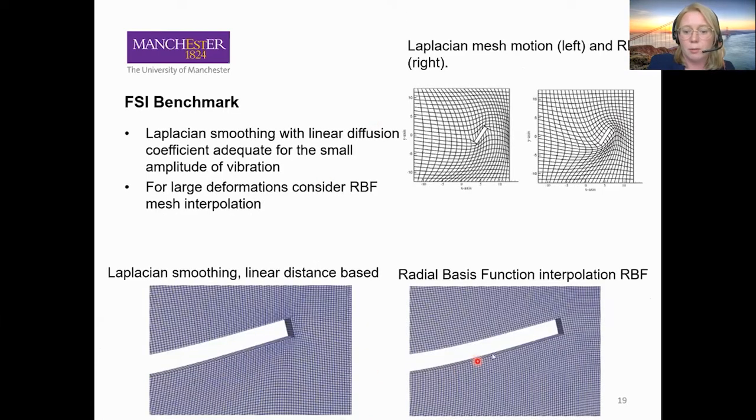Just a couple of words about the Laplacian smoothing: there was already a dynamic mesh training session yesterday, so I won't go into much detail, but linear distance-based diffusion is very good for small deformation. For large deformation, I would consider radial basis function, which is implemented in solids4foam.